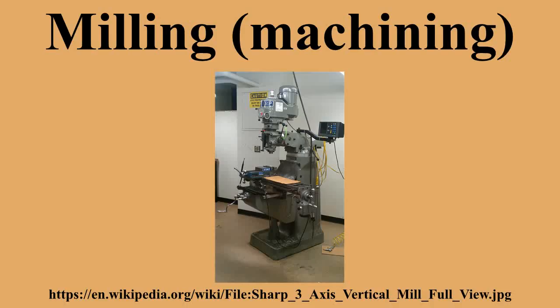A typical bed has X and Y travel, and is between 3 and 4 feet square with a rotary table or a larger rectangle without a table. The pendant usually provides between 4 and 8 feet of vertical movement. Some mills have a large integral facing head. Right-angle rotary tables and vertical milling attachments are available for further flexibility.